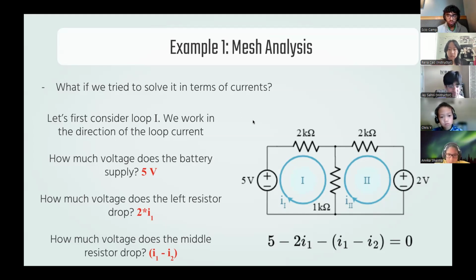But for now, remember V equals IR, that's Ohm's law, right? If I have V equals IR, and I split that I into two different values, like I1 and I2, then it's just the distributive property. V equals (I1 plus I2) times R is V equals I1R plus I2R. The fact that Ohm's law is linear, I times R equals V, is what allows us to do that. Adding up these different loop currents is completely permissible because the voltage drops also add in the same fashion.